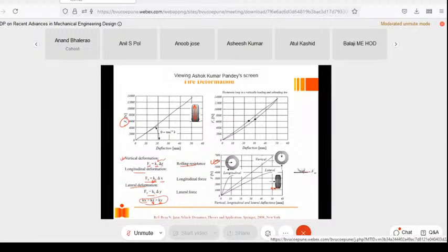So how do you explain this lateral effect? Through this particular picture I would just like to explain. So here you see, when you try to turn your vehicle, the lower portion of the wheel gets deflected. This will go outward and this will remain at the road. So the lower portion will deflect. Because this tire is made of rubber and it has elastic property, it will try to bring this back. The force which tries to bring it back is called the lateral force. So from the top, this is how basically it happens. So this is what is called lateral force.